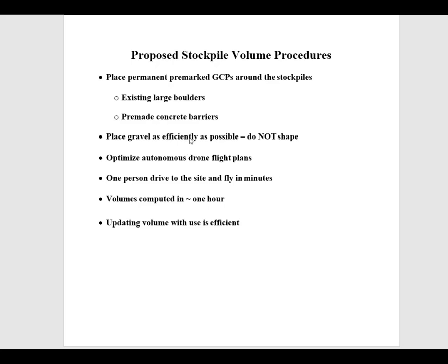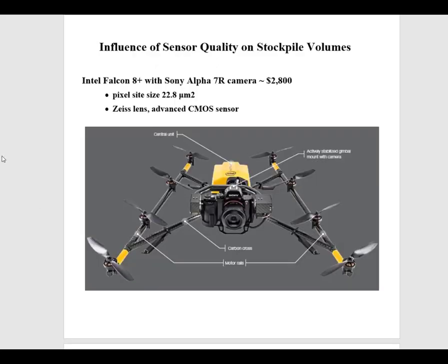So placing the gravel stockpiles efficiently, don't worry about shaping them. Design automated drone flights. So one person could go to the site, just launch the drone, fly the predetermined pattern, go back in the office, and then have volumes computed in, well, maybe an hour is optimistic. Drone processing takes some time, but while it's processing, you can do other items, and then you can update the volumes without having to reshape the pile. Fairly efficient.